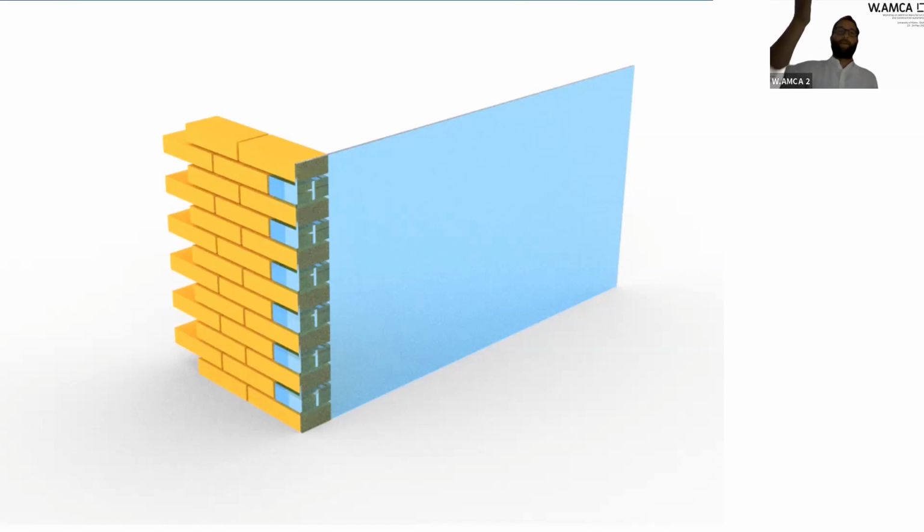But I think we will face the same issues as you with your resolution in clay printing, because those notches in between each layer will be the failure criterion for additive manufactured glass components to break, because you always have stress concentrations at each intersection.